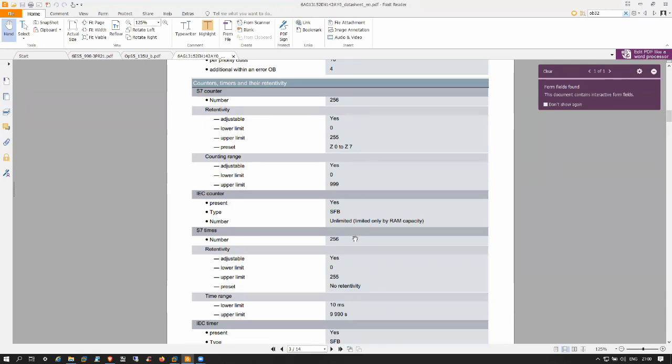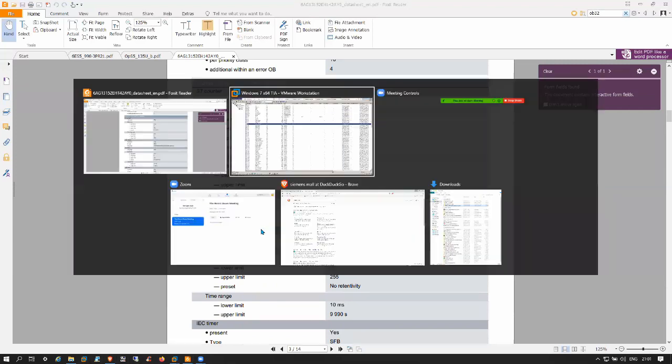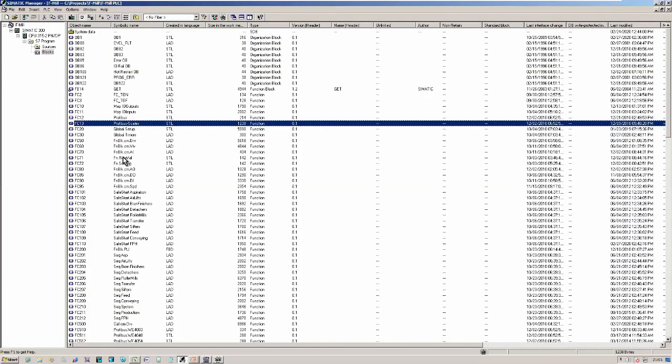I just avoid timers. We use our data blocks to have the preset for the timer and the actual, and we count in the actual using that 1 sec flag. We use that to count how long the timer is on. Let me just quickly digress.